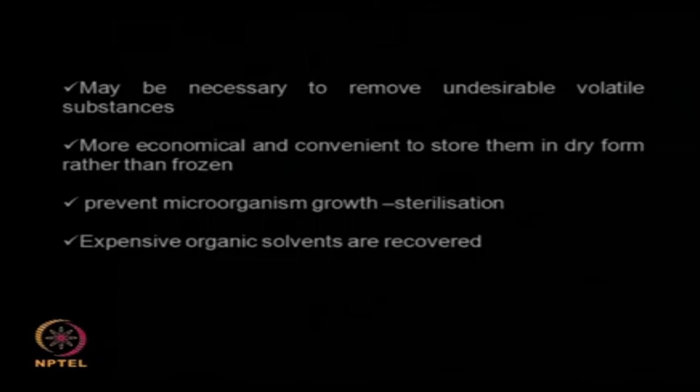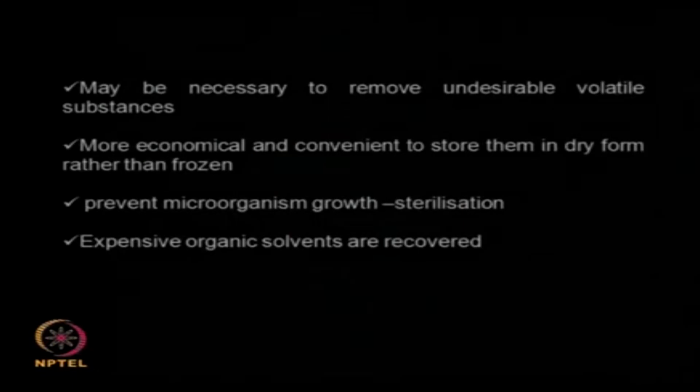And sometimes you may like to remove unwanted volatile materials. There could be a very small amount of solvents present which you do not want to be carried over, because when you transport a solid material with some amount of solvent, then during the transportation as well as during the storage the solvent may evaporate and the vapor pressure will be generated by this solvent. And also it is more economical and convenient to store them in a dry form rather than in a frozen form. And then drying also acts as a sterilization, that means it kills whatever bacteria or microorganisms present.